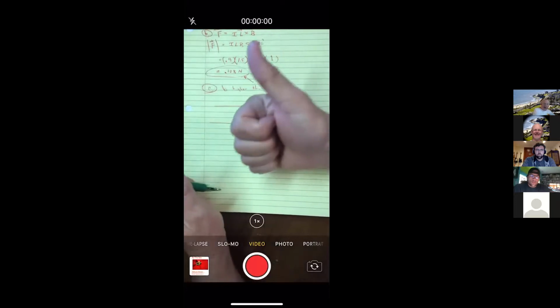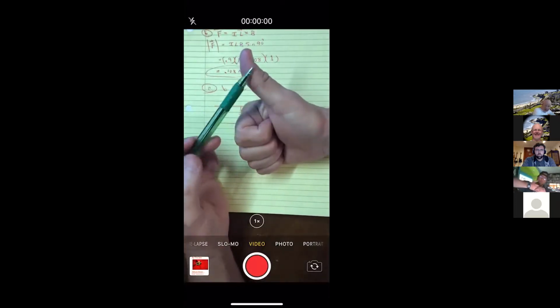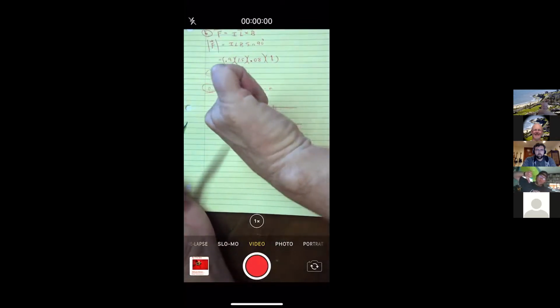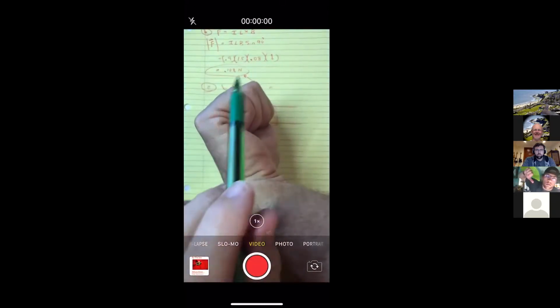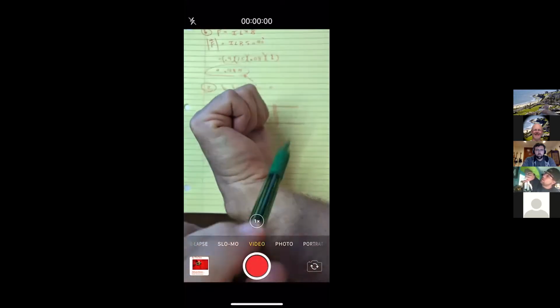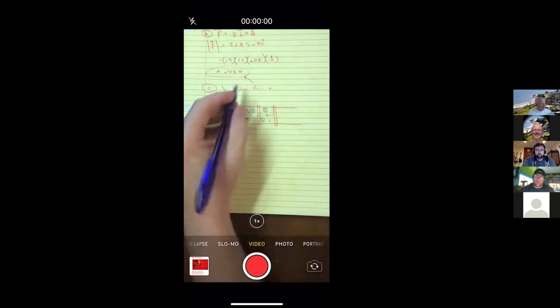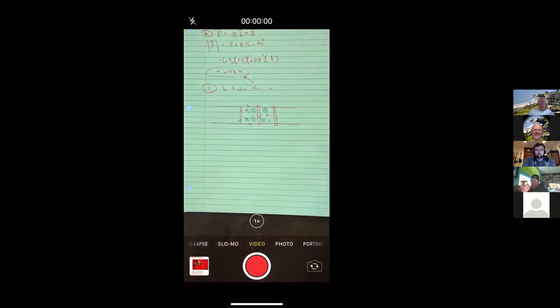So I'm going to take my right-hand rule. Remember, my thumb is going to be the direction of the flux, so I'm going to point my thumb down. I want my current in a direction. If I look at my fingers now, my fingers are curling around in a clockwise direction. Oh, okay, I see. My thumb points down, yeah. So the current would be going in a clockwise direction.